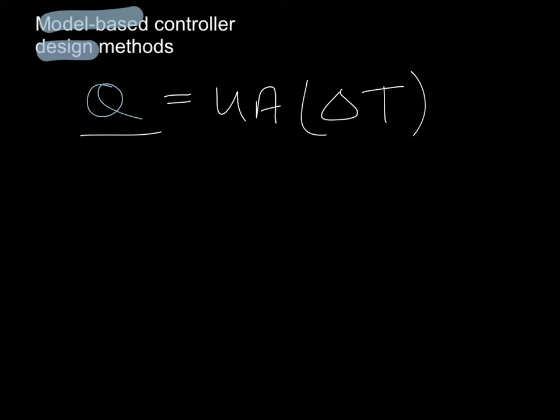In other words, we start with known values for U, A, and delta T, and we calculate the duty. So this is known as the rating problem, but this is based on a certain model of how heat is transferred.